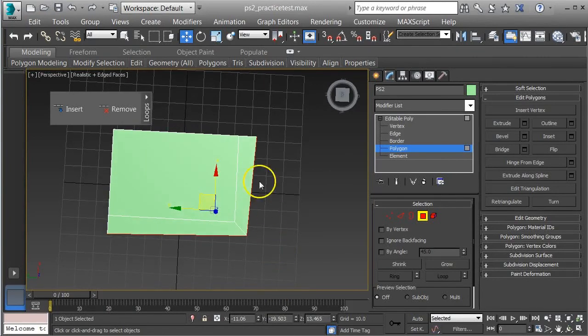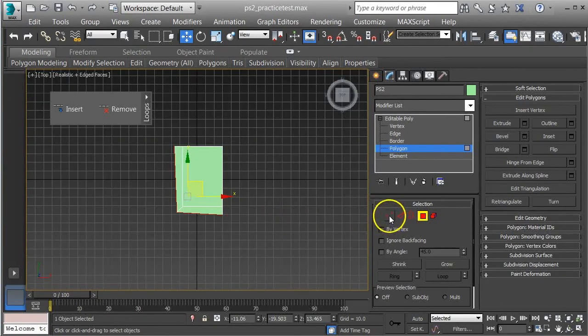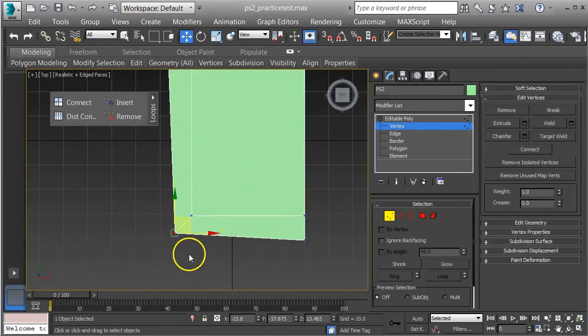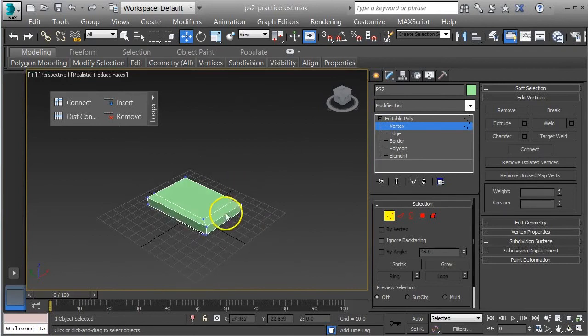If we look at this, you can kind of see that it's crooked. And so we can fix this one of 2 ways. We could go into the top view, and I could move this point over and line it up, right? I could look at the coordinates for these points. So these points right here are on the X and Y, right? We're going to be Y here, -40. So we grab this one and we could just simply put it in there, and you see it straightens it out. Then we grab the coordinates for this one and apply it to that one. Right, that's one way.